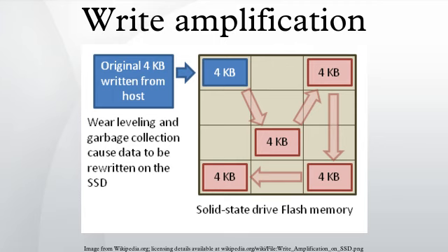Reads do not require an erase of the flash memory, so they are not generally associated with write amplification. In the limited chance of a read disturb error, the data in that block is read and rewritten, but this would not have any material impact on the write amplification of the drive.